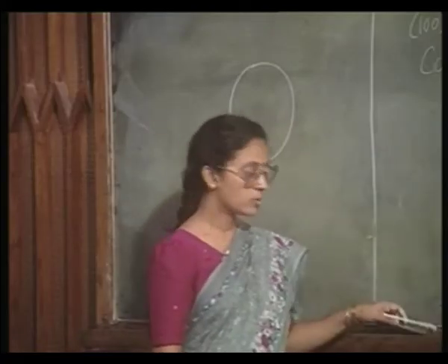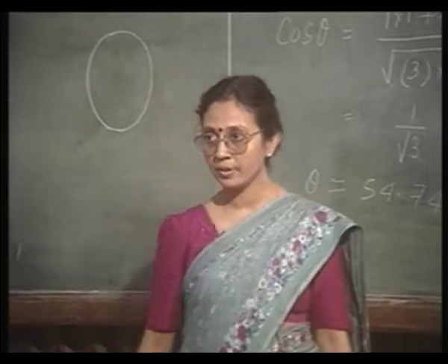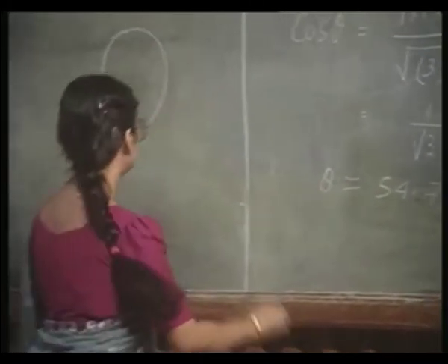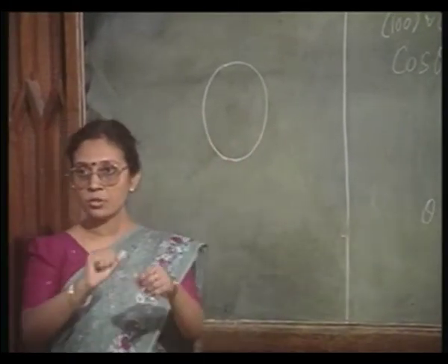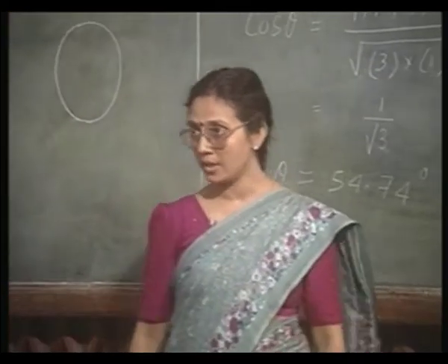Big disc of silicon. I would like to cut pieces from here. How does one cut? Usually what is done is you scribe using a diamond tipped tool. You scribe like that and then you try to cleave it, break it along the scribe lines.